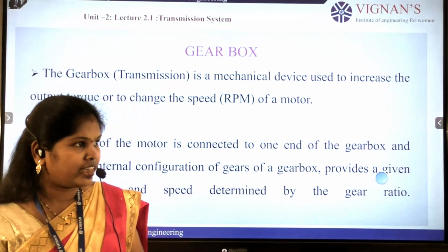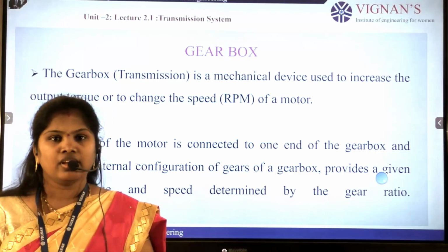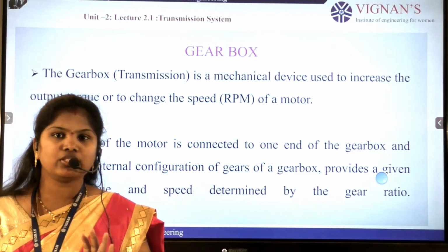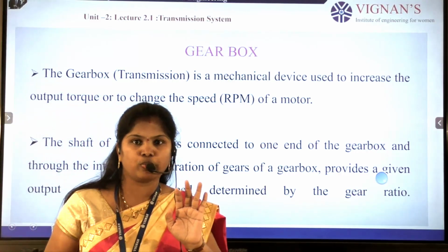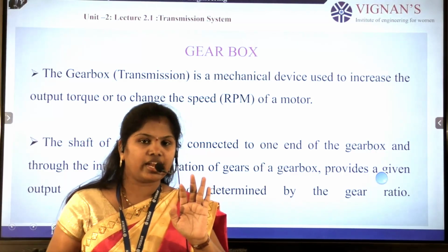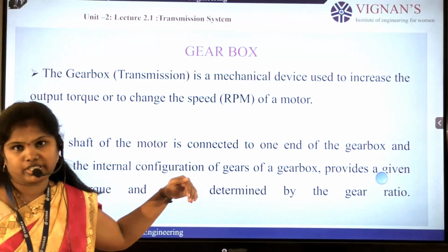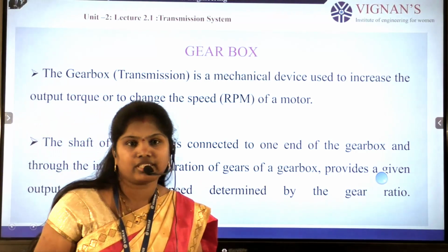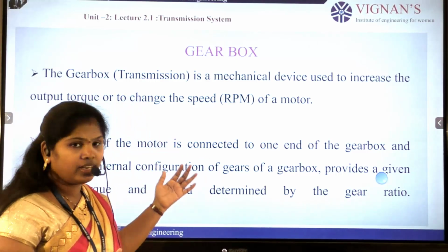An example for the gearbox function is when the vehicle is going up a hill. On a hill we need the vehicle at low speed with high torque. We have to generate high torque in the vehicle while the speed is less. For that we have to use different gear speeds. Generally we discuss the first gear, second gear, third gear and reverse gear for general gearbox units.